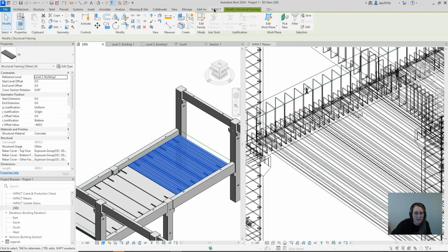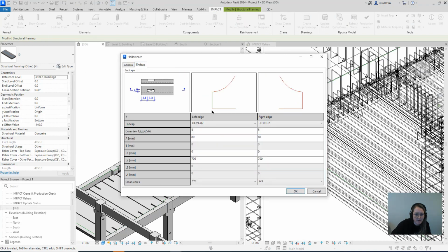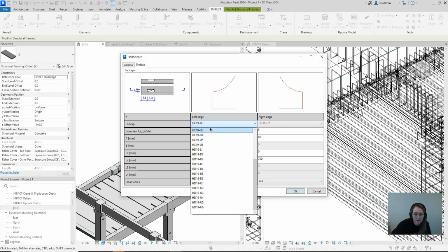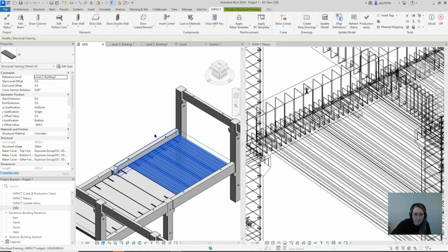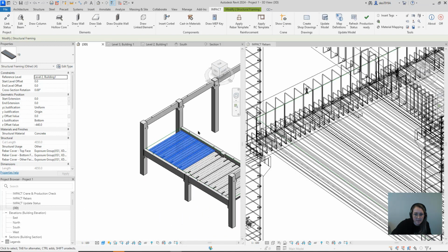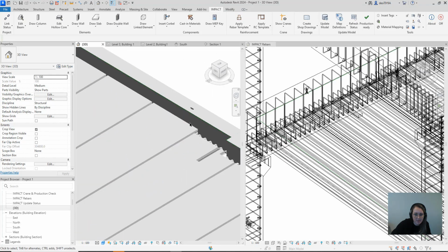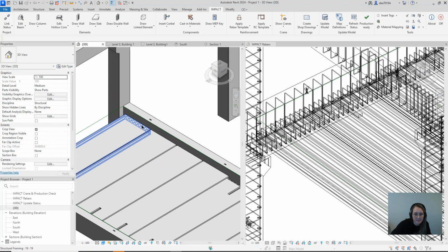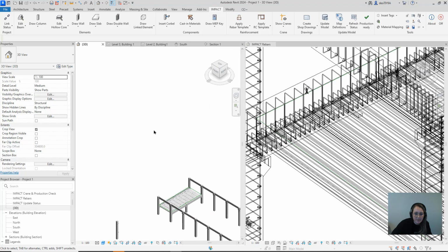So you can just say, again, edit for multiple elements, and you can either select all edges or just one of them. It's up to you basically, and it's just important that you have this very powerful tool that can do changes like this in the geometry in a couple of seconds. So this edge right now is just straight.